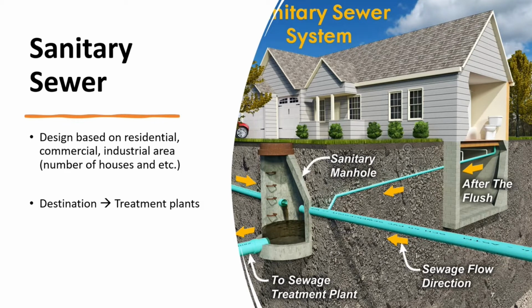But if that runoff is flowing over the manhole lid of the sanitary system, then clean water is entering the sanitary pipes, and that is not something that we expected to happen, because the sanitary sewers are not meant to allow any runoff entering. So that's one of them.